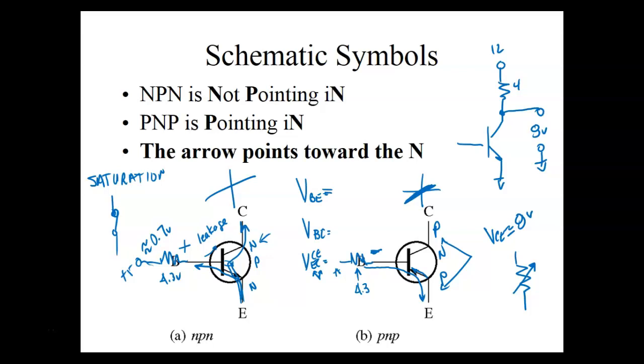So what we're doing is we're controlling the base current with this. Right now, we're controlling that base current with that resistor right there. So what happens if this voltage goes up, this guy here is dropping about what? 0.7 volts. So if this voltage goes up, let's say it was sitting at 5 volts, it goes up to 6 volts. Now this guy right here is not dropping 4.3, it's dropping 5.3.